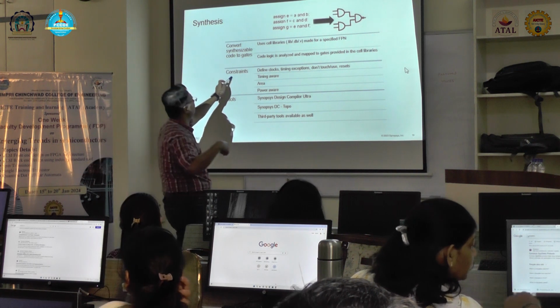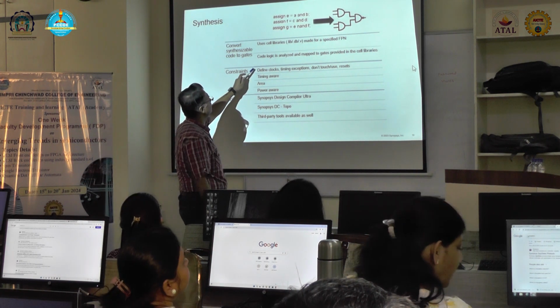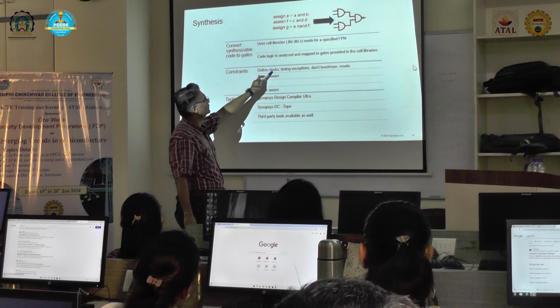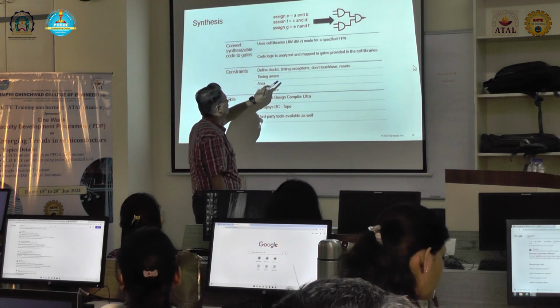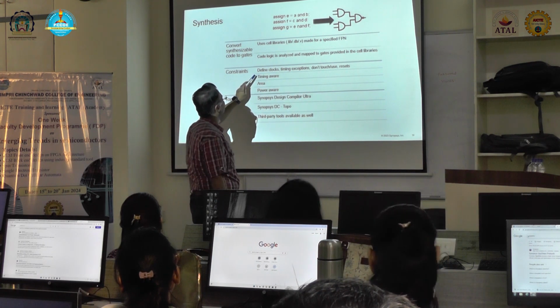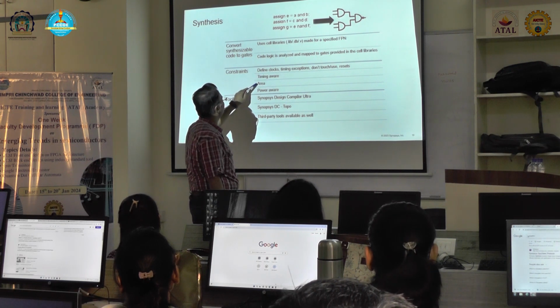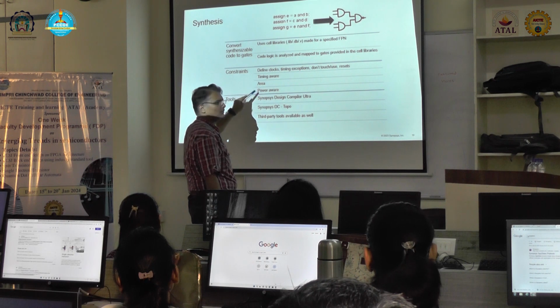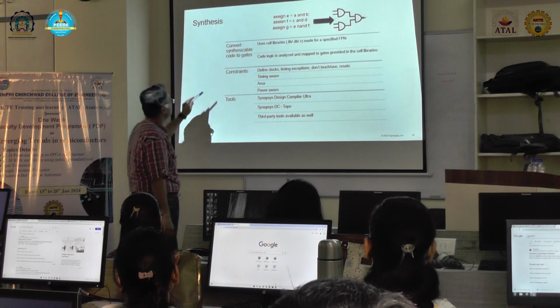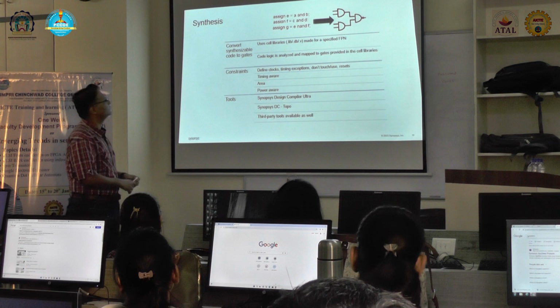So in the constraints that we provide to this tool, as I was saying, we define the clocks, we define the timing exceptions, we define don't touch. We have defined the frequency, we have defined the area, we have defined the power. So these are the constraint inputs that we provide.